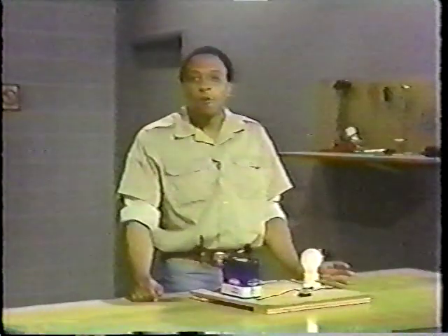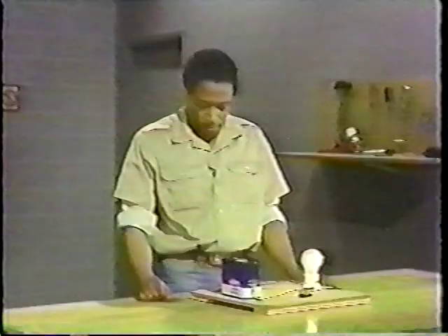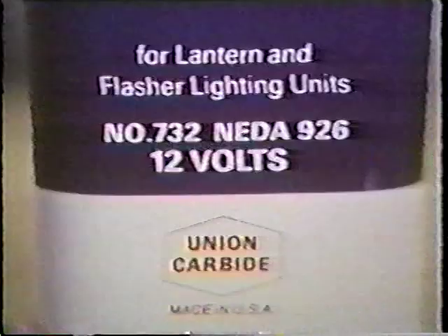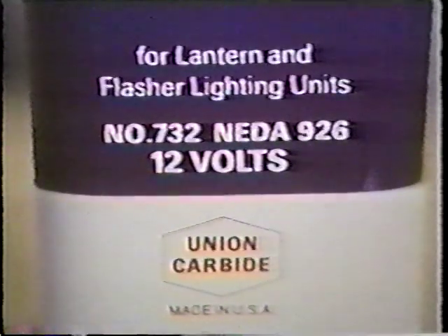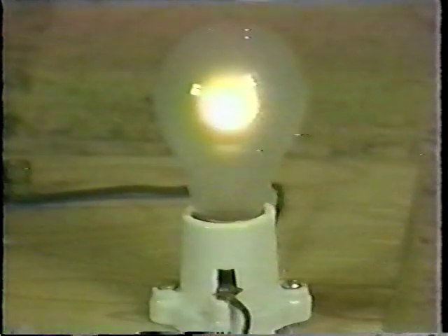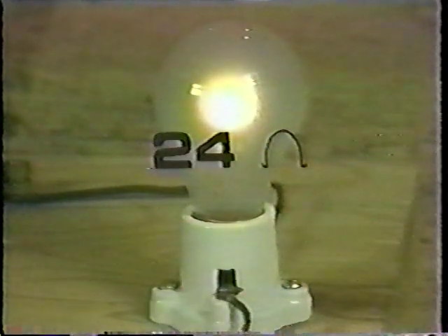If we know what the voltage and resistance in this circuit are, we can use Ohm's law to figure out what the current is. To find out what the voltage and resistance are, you might measure them with a meter, or the values might be printed right on the component. Just for the record, we know the values of voltage and resistance in this circuit because the battery's got it printed right on the casing. And we measured the resistance of the light bulb and got 24 ohms.